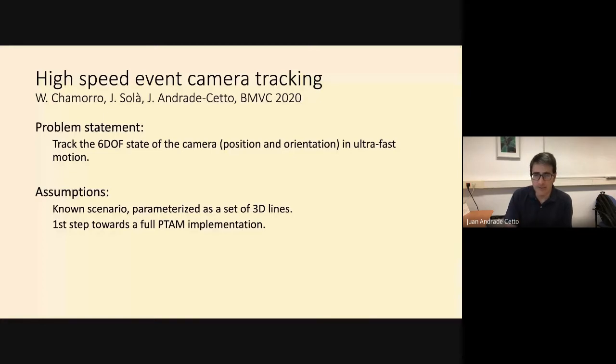On an event camera, you get the polarity: positive polarity in red, negative polarity in blue. And you will see lots of events here because what you are seeing is chunks of 10 milliseconds displayed on the image, superimposed on top of a conventional camera image. But in reality, what you get is just one event at a time at different timestamps. And we process all of those events, each of them when it occurs.